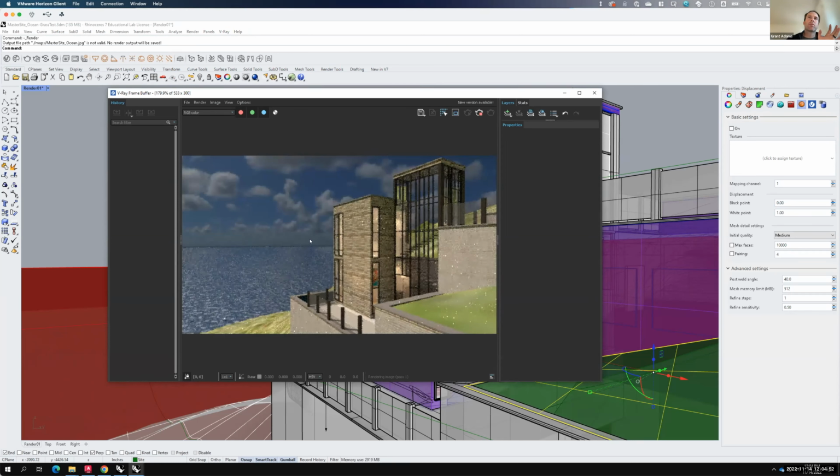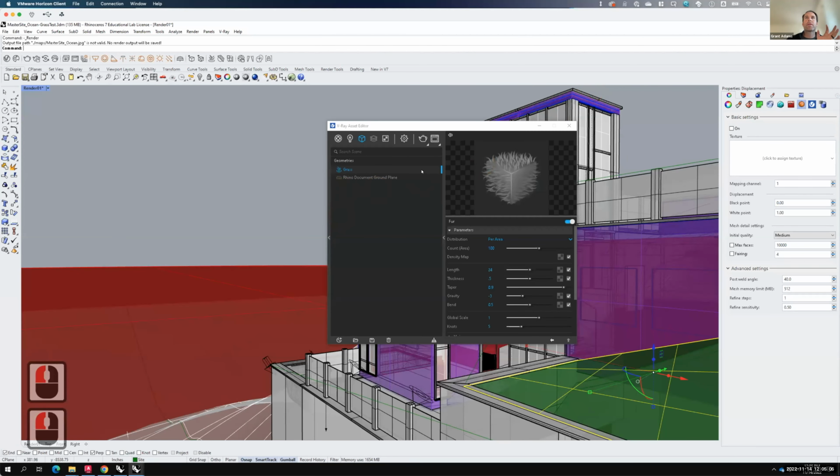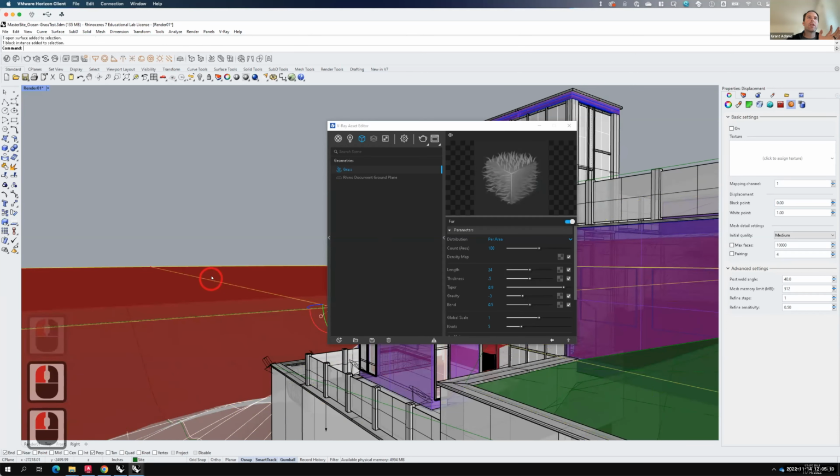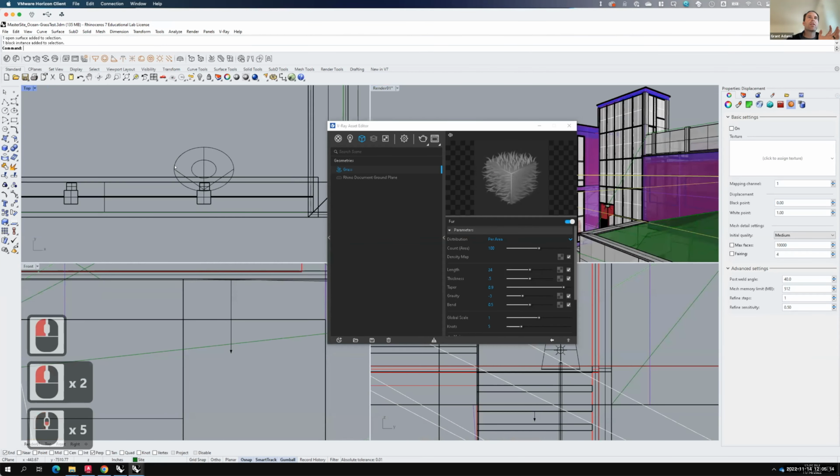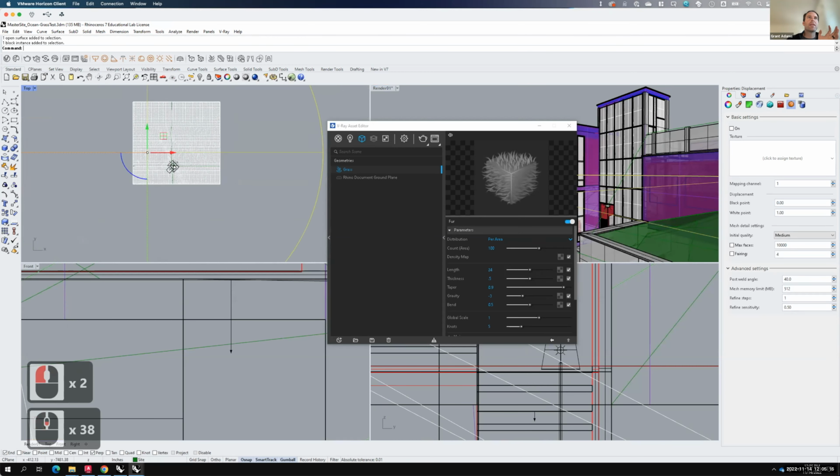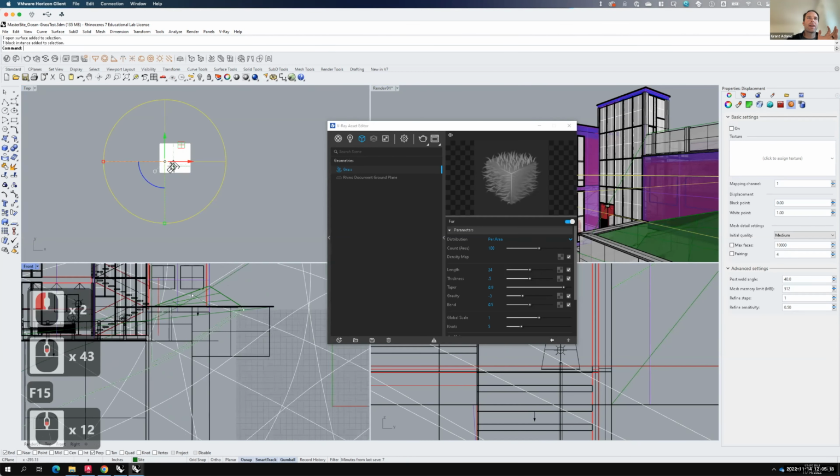While I'm rendering this, since we're on the day render settings, I am noticing that I'm getting a faint little bit of horizon there. That's causing a problem. So I may want to tweak that out just a little bit, and I can do that. I've done this for a few of you during the check-ins. What I can do is take this giant dinner plate in the ocean and do a scale to raise up where the horizon is. So I can kind of fake it a bit.